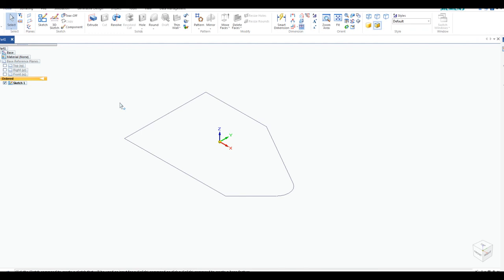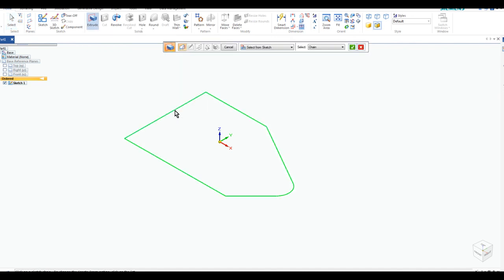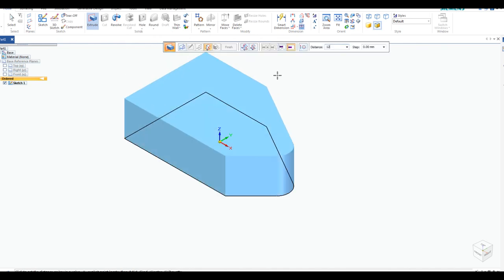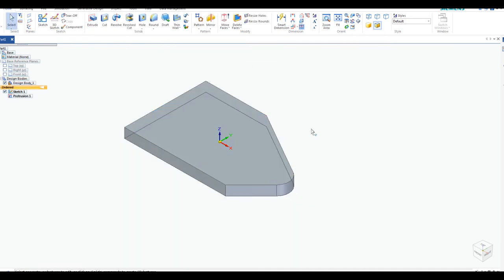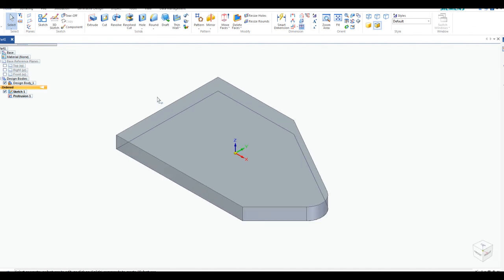Finish all commands. Alright, so it's going to be a straight extrusion. If we take a look at our section view, the thickness is 12. So I'm going to click on extrusion, select the profile, enter or accept, either one. And then I'm just going to type in 12, enter, and pick anywhere in space, finish, and cancel. And now I have my first solid, which is the base itself. Let's put it into scope.